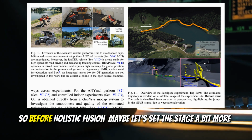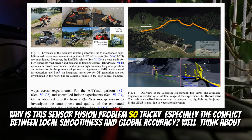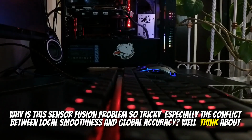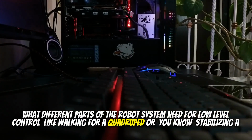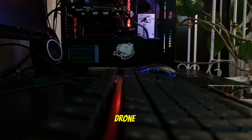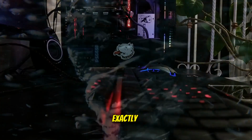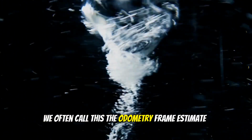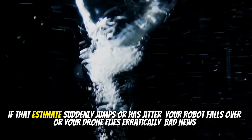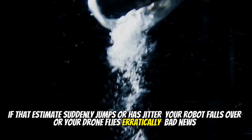Sounds good. So before holistic fusion, maybe let's set the stage a bit more. Why is this sensor fusion problem so tricky, especially the conflict between local smoothness and global accuracy? Well, think about what different parts of the robot system need for low-level control, like walking for a quadruped or stabilizing a drone. You need state estimates coming in super fast, maybe hundreds of times a second. Exactly. And they need to be incredibly smooth and locally consistent. We often call this the odometry frame estimate. If that estimate suddenly jumps or has jitter, your robot falls over, or your drone flies erratically, bad news.